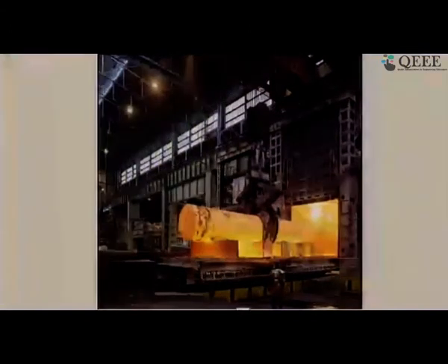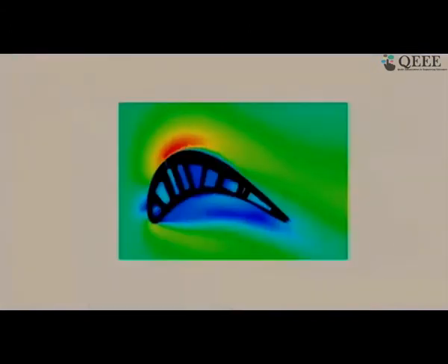So that's an example from one type of manufacturing. This is a picture of a gas turbine blade. It's a simulation. So hot gases go over this blade from left to right, and in the process they generate a force in the upward direction, and this acting on a lot of blades produces a torque on the drum, and that's how you get power output from this turbine.